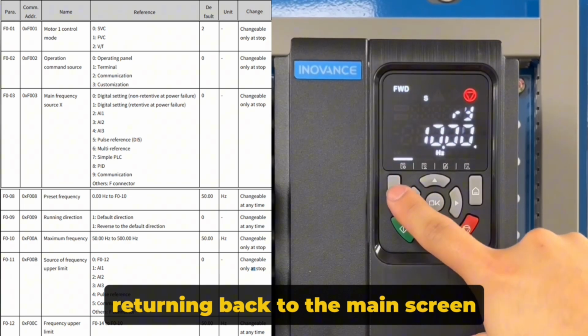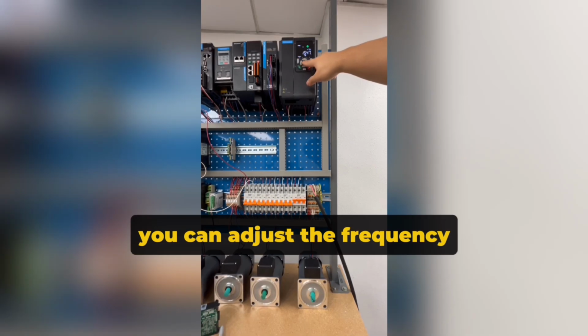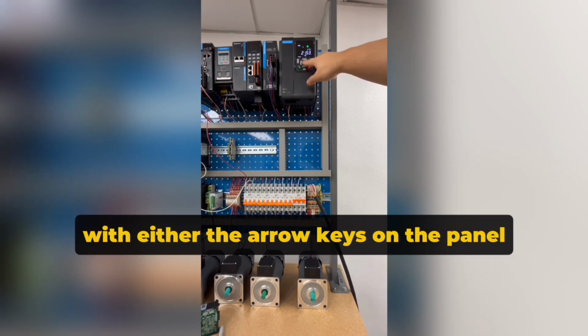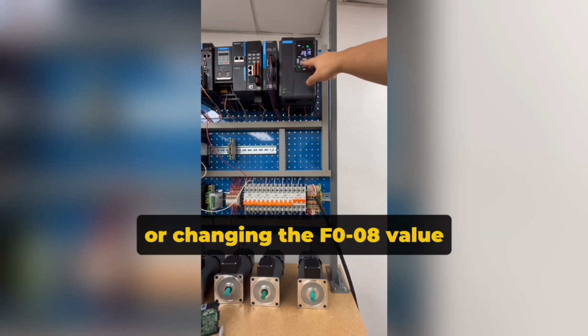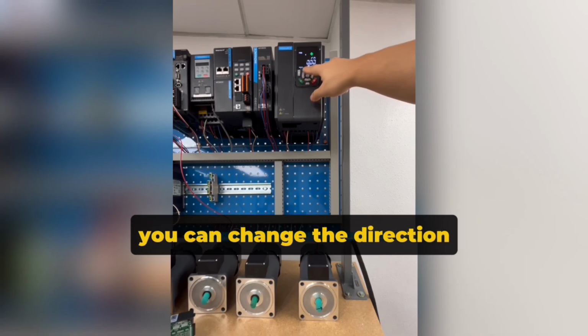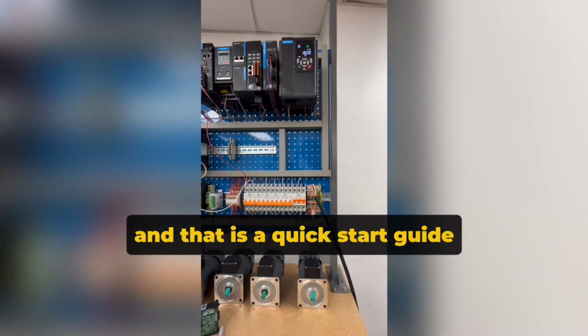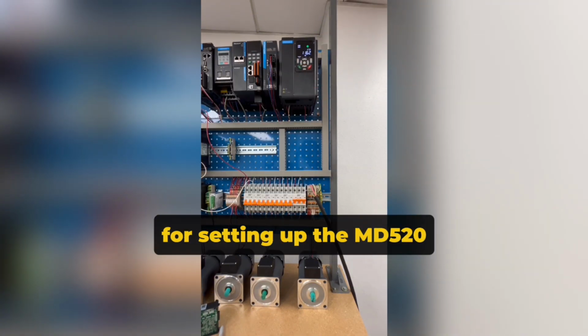Returning back to the main screen, we can now press the Run button to start moving. You can adjust the frequency with either the arrow keys on the panel or changing the F0-08 value, which can be done real-time. You can change the direction the motor is running real-time as well. And that is a quick start guide for setting up the MD520.